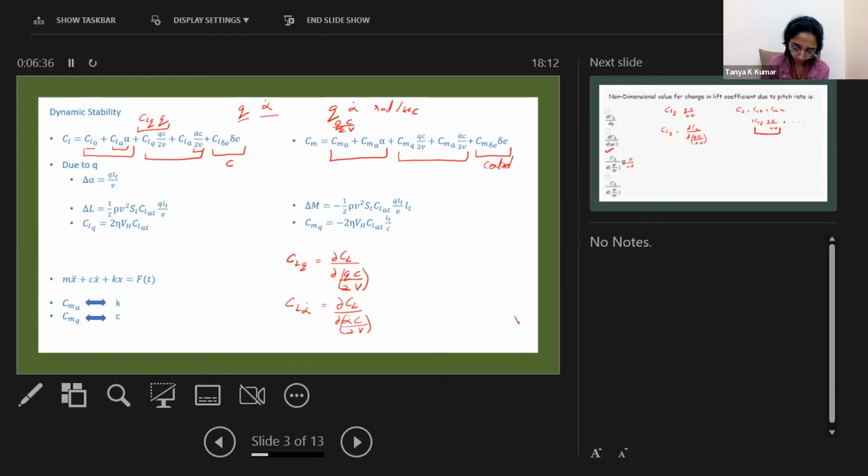So now what happens when the aircraft is subjected to a pitch rate, when the aircraft is changing the theta? So there is a Q, a radian per second component. What are the changes that are seen in the aircraft? There is a change in the angle of attack at the tail, right? So this is delta alpha tail. When the aircraft was initially, so this is the fuselage reference line, and it pitches up. So this was the horizontal tail. So there is a change in the angle of attack at the tail. How much does delta alpha t change? Approximately it is QLT by V.